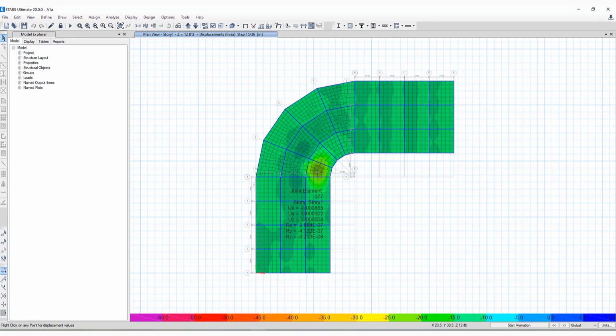So these results are available for each step as well as a range combination of all steps. This range combination gives the maximum and minimum of all possible patterns of loaded slab panels. These range combinations later can be used for design with any gravity load combination, including applicable load factors from the combination as well as live load reduction factors.